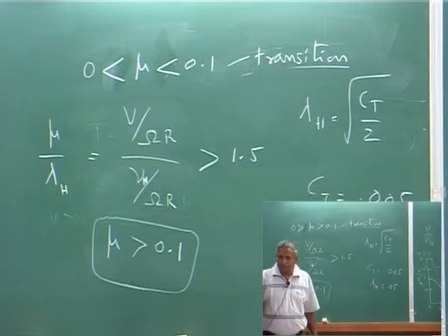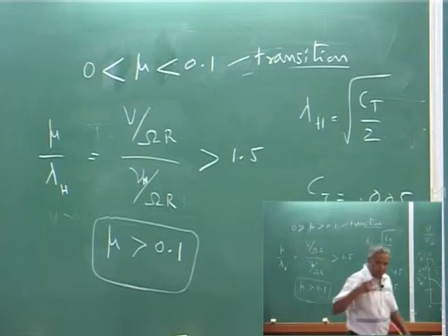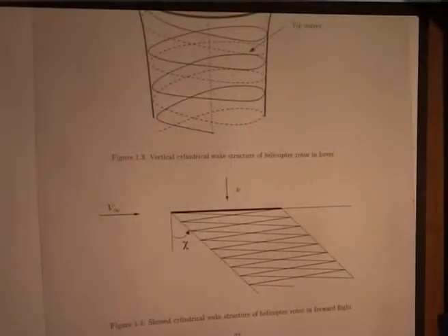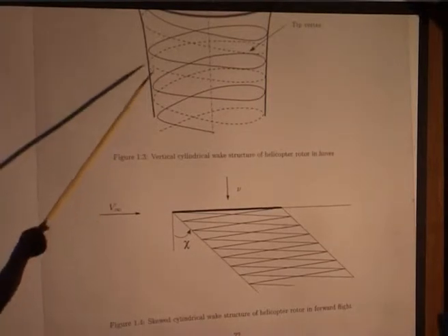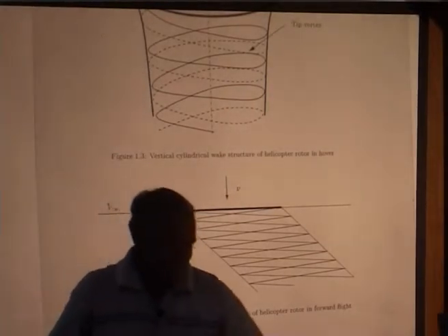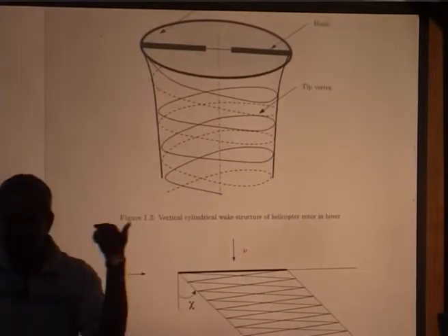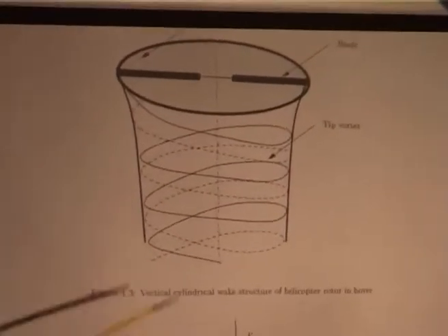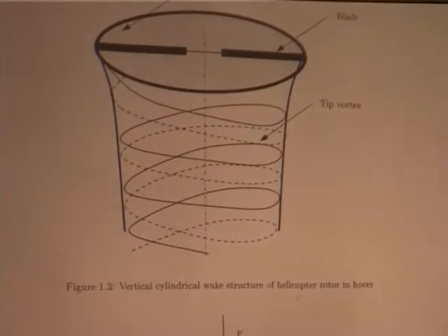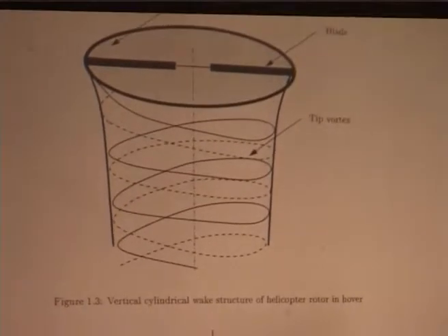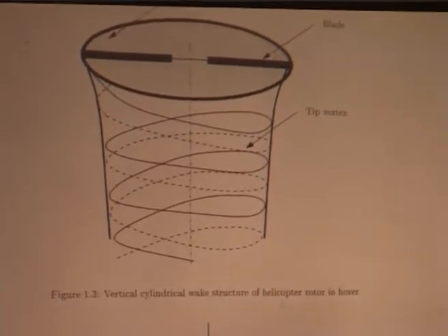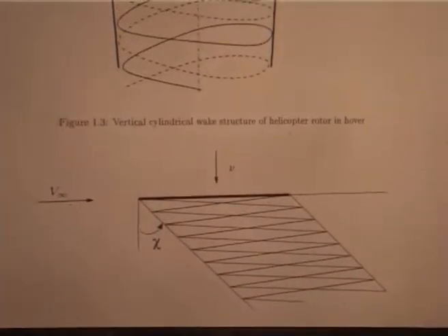That time the rotor wake, I will show, because when you start the forward speed, what really happens is, initially the rotor wake, in the sense whatever is the disturbance coming out from the rotor blade, the lifting line theory or anything, the wake comes straight below the rotor. But once you start moving forward, the wake is in a skewed cylinder.